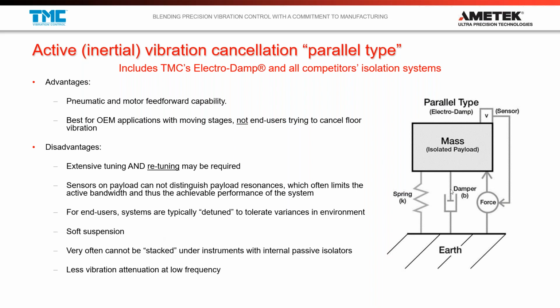But I digress. One of the things that you're always going to be dealing with in a parallel type system is the fact that there's always going to be an input from the floor that's amplified commensurate with the resonant frequency of whatever is bearing the load of the system. So say this is a soft spring and you've got a 2 Hertz resonance. Well, that 2 Hertz resonance is always going to be amplifying floor input and always feeding into here. And so right off the bat, you are spending a lot of your cancellation energy canceling out the system's own resonance. And then you have some limited bandwidth available for everything else that's going on top of the system.